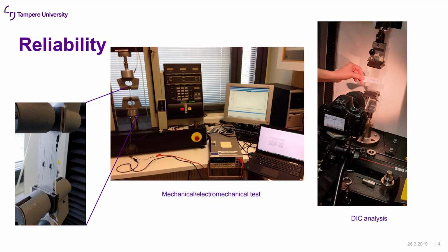We do reliability tests like some basic tests, like stretching and cyclic tests, to see the lifetime performance of the device. And we also analyze the system by DIC, which is very important because we can track the strain during the deformation, especially from a modeling point of view.